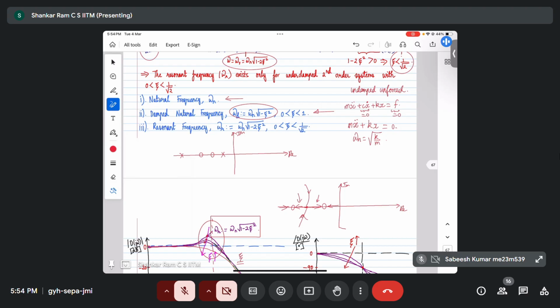It's like an origin and a destination. This is the destination, so the origin has to be somewhere. The origin comes from somewhere in the imaginary axis or some other place, and the two branches intersect on the real axis. That is why it is called a break-in point. Why? Because after hitting this point, they break into the real axis and go along that real axis.